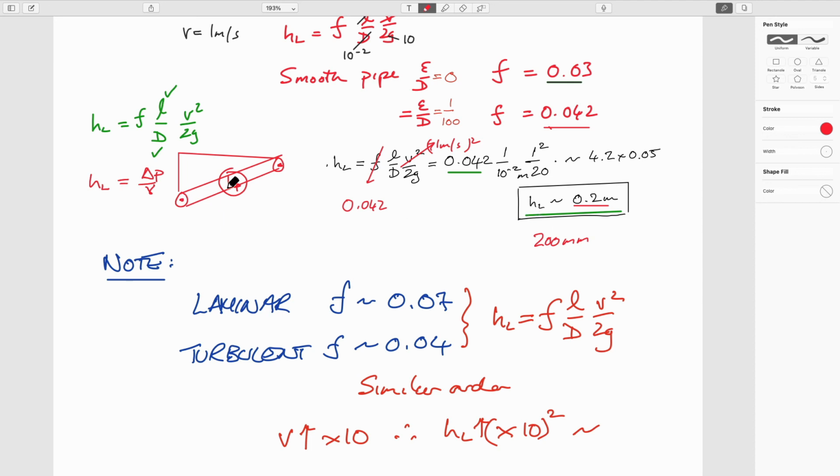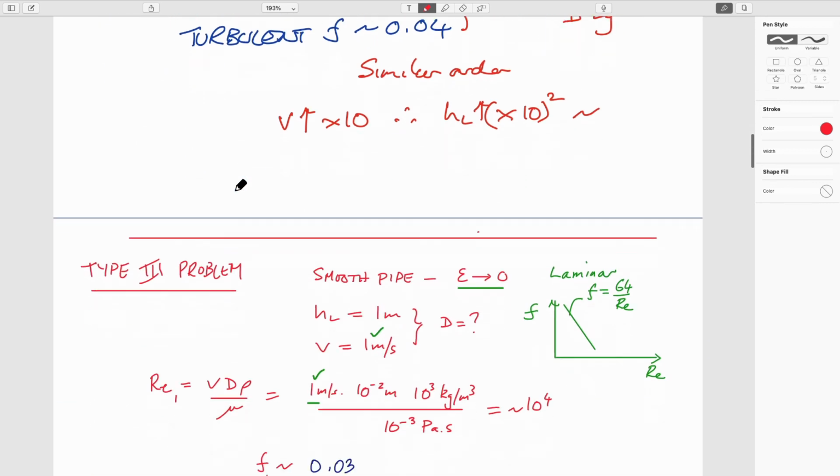So the fact that you're getting a flow rate is either driven by the fact that you have an upstream pressure which is doing that, or you have a pump which is driving it along, or I guess you could think of it by the fact that this pump is providing this head at the upstream end to be able to move it along the pipe. That's physically what you're doing. So if you had a pump here that was pressurizing a tank, then it would pressurize the tank to this pressure, and they're kind of equivalent to each other. So that's kind of it.